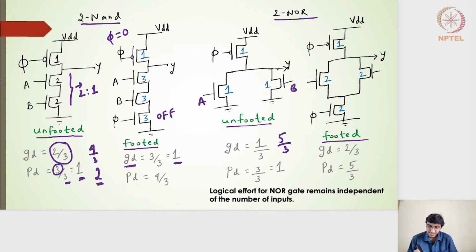And the parasitics will be nothing but 1 plus 1 plus 1, that is 3, the output node capacitance divided by 3, which gives me a value of 1. Again, the CMOS structured 2 input NOR gate gives a parasitics of 2, whereas here the dynamic logic family gives a parasitics of 1.